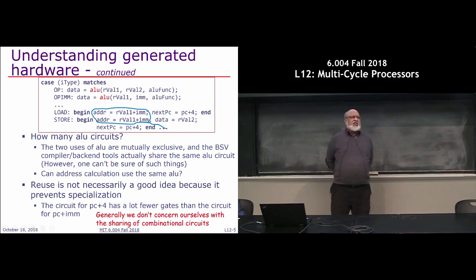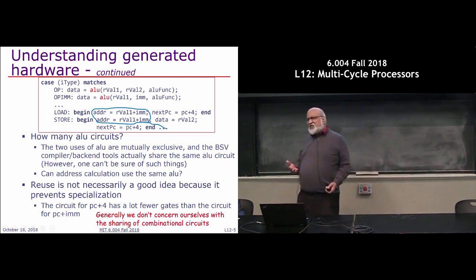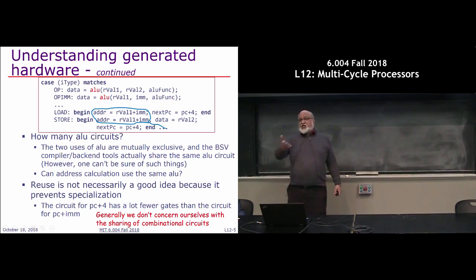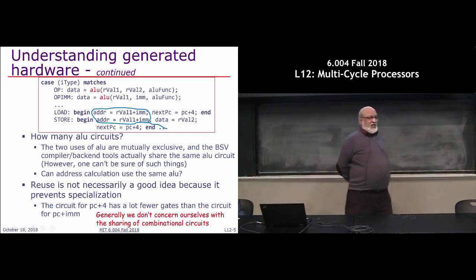In some specific case, if there is a huge combinational path, you may want to go and re-examine it. You say, did I use a good algorithm for doing add or multiply or whatever? And you saw examples of that. You had the carry look ahead adder, right? Which is a distinctly superior circuit from the point of view of delay through the system.